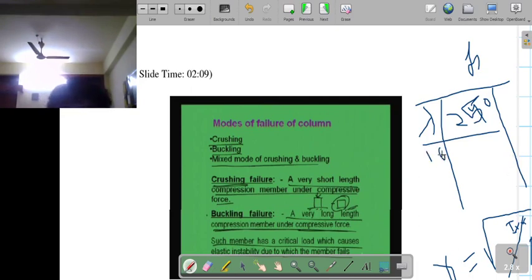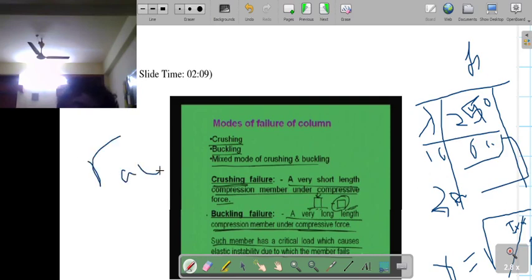Here defined lambda values start from 10 and go up to 250, and for each defined Fy value, the value of sigma is given here. So you can directly refer to this table and find the value of sigma. Suppose your lambda value comes as a fraction or in between, let's say between 10 and 20, then you have to do interpolation. This is how we can find the value of sigma SC from the table, or you can use the equation given in the code book.